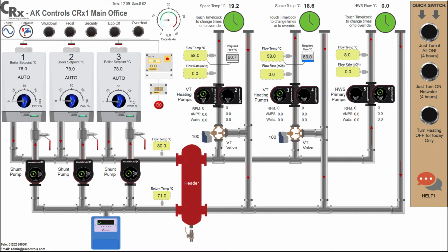temperature heating circuit. 6 pulsed inputs are included with the package, one of which uses an electric meter included with the control panel. This logs the total power usage of the plant. A Modbus RTU communication bus is also available for use in collection of pump data or additional electricity meters. The optional remote monitoring package can collect all the metering data and make it available to the user from any device with a web browser and an internet connection.